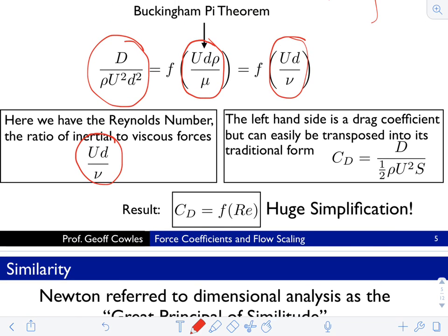The left side we will manipulate. So this is one way to non-dimensionalize drag. Traditionally, instead of rho u squared, you use a half rho u squared. You use the true dynamic pressure. That is just convention. That half does not have to be there, but by convention it is there and will always be there. And what shall we use to non-dimensionalize, what length scale?